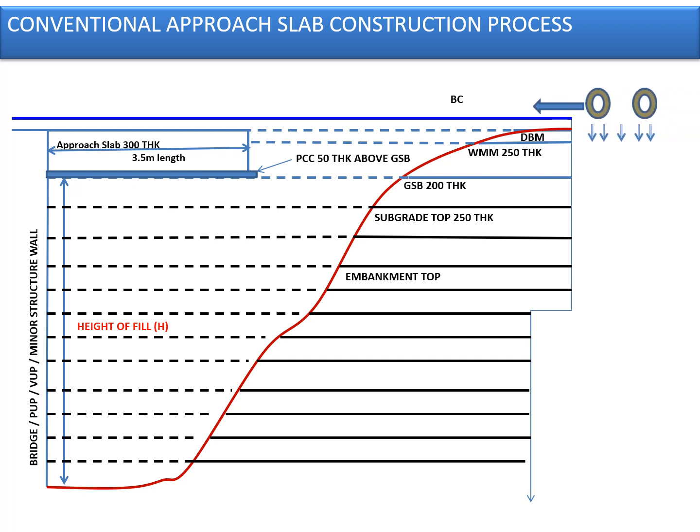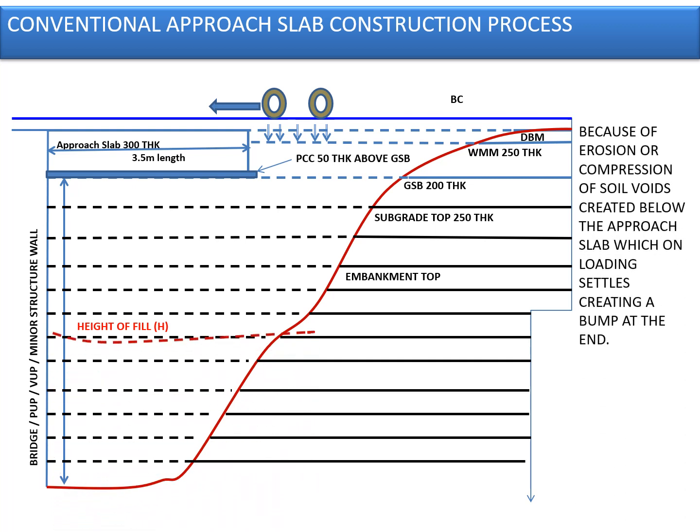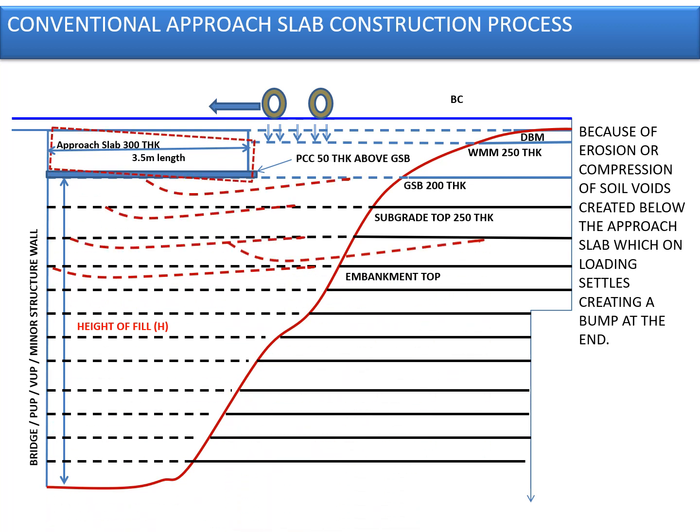Now the idea is, as the vehicle moves, because of the smaller section of these areas being filled up after the completion of the bridge, the possibility of pre-compression or localized consolidation is high in these areas because of the lesser compaction. So as the vehicle moves, with the application of brakes and all, the chances of movement of soil in these locations are high, thereby making the approach slab twist from the bridge locations.